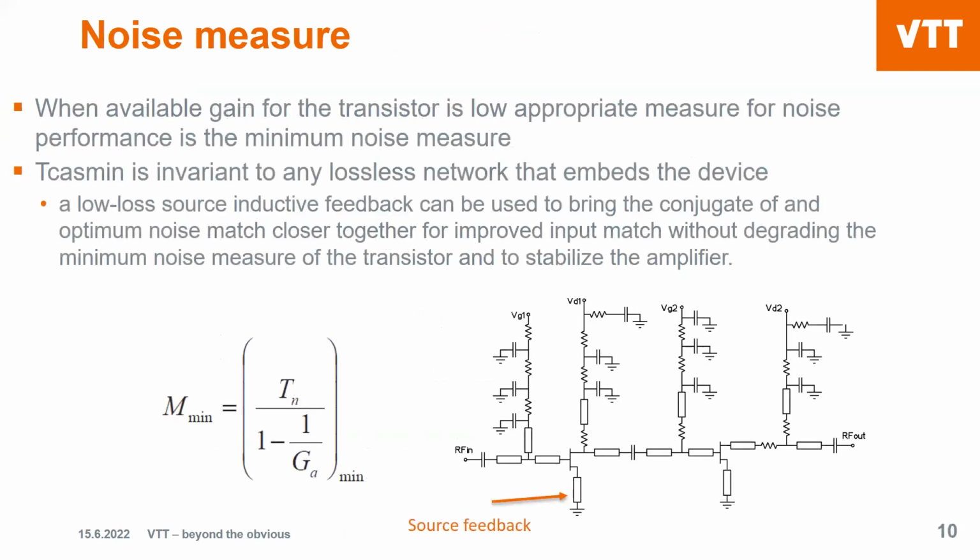What determines the number of fingers, in other metrics? It only affects the output power. And it also assumes that when you double the number of fingers, you also double the current. It's like a cell that you copy, so you burn twice the power too, because it's a fixed cell.